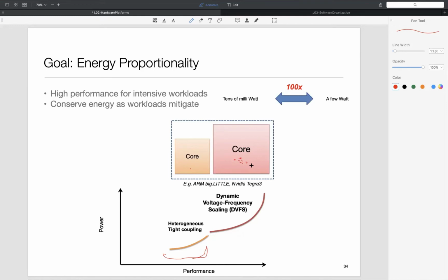Several of the high end ones, partly because the workloads have increased, but partly also, remember I said earlier that it is better for me to operate slowly and have more hardware because of the DVFS effects. So it's better to have more cores operating slowly as opposed to a single core operating fast, in general. So by spreading, parallelizing and operating at a more efficient level, it kind of pays off.